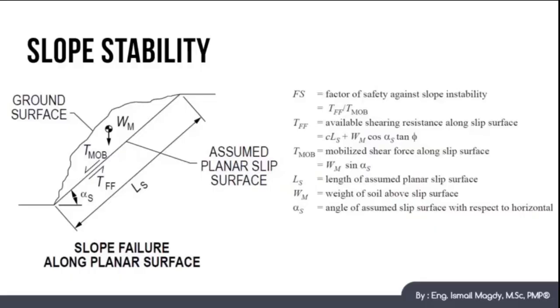During construction, many times we need to dig trenches, and sometimes instead of providing a shoring system, we can rely only on a sloped embankment, as we can see here. The stability of this embankment needs to be studied to avoid the soil sliding and the slope failure due to the shear failure, as we have learned in our previous video.